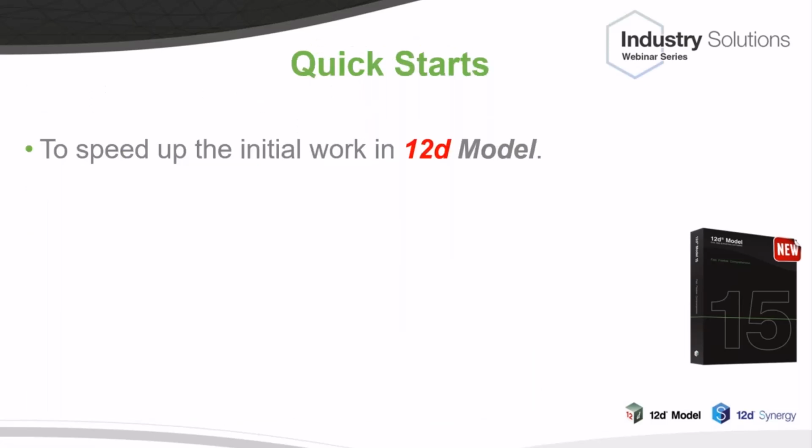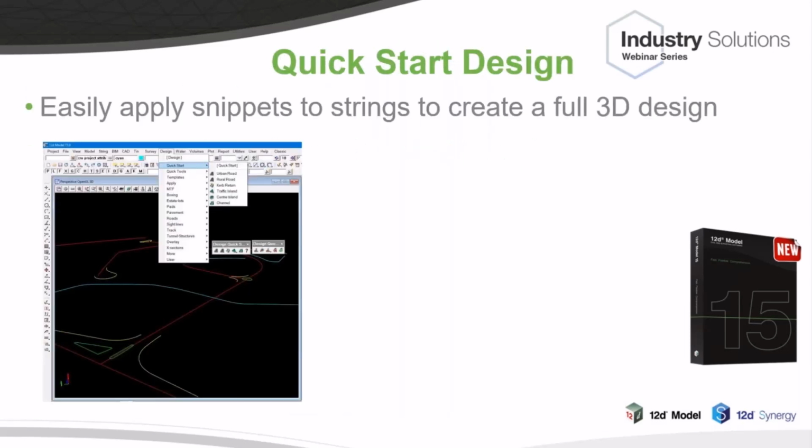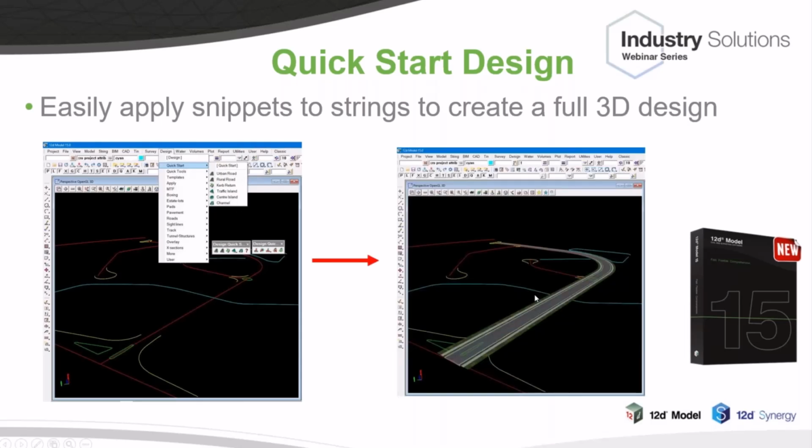To speed up the initial work in 12D model, we have a number of new things called quick starts. There's one for quick start design, which allows you to easily apply a whole lot of set snippets to build full 3D roads very quickly from just your alignments. So basically you pick one of them, pick a string, and hey presto, all your pavements and things that you've defined are in there already.